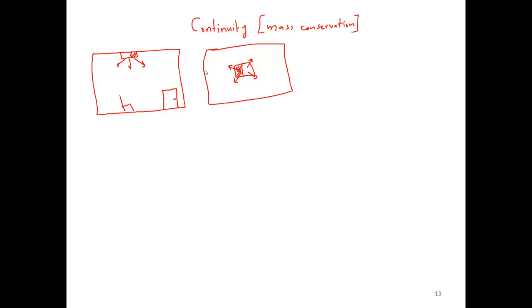Okay, so now you have almost half the area. Remember there are some other rooms that are taking the airflow rate, so if it's well balanced, then the same amount of air would still go through this. What would happen is you will start hearing some noise. Now why is that? It might be pretty simple for us as of now, and it might get complicated as we start looking into the equations. Remember that when we go to Bernoulli, remember this example, and if you want, ask me again to try to relate what happens here.